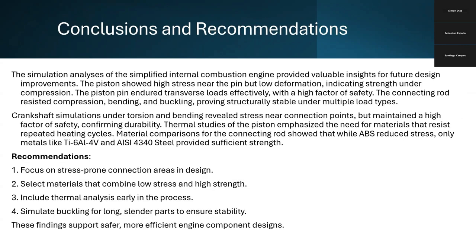For the conclusion, the simulation analysis of the simplified internal combustion engine provided valuable insights for future design improvements. The piston showed high stress near the pin but low deformation, indicating strength under compression. The piston pin endured transverse loads effectively with a high factor of safety. The connecting rod resisted compression, bending, and buckling, proving structurally stable under multiple load types. Crankshaft simulations under torsion and bending revealed stress near connection points, but maintained a high factor of safety, confirming durability.